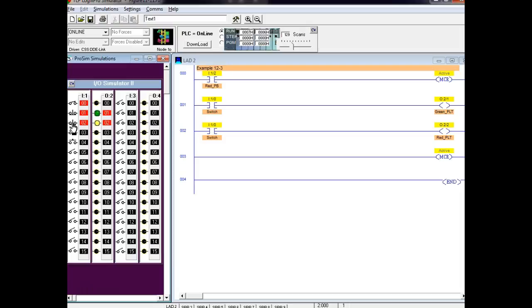So they have it as an examine open. But if the MCR is not active, it does not turn the output off. No, read it. I got your book. Therefore, when the MCR coil is de-energized, the rungs between the two MCR instructions are turned off.